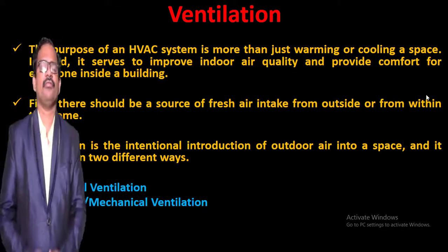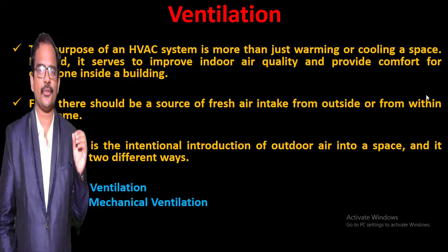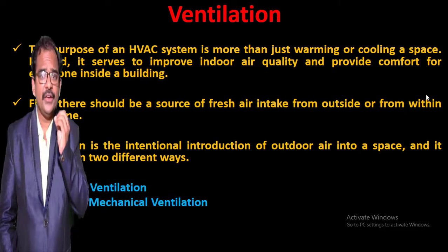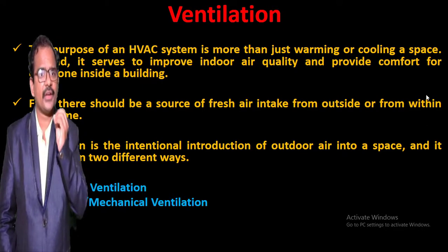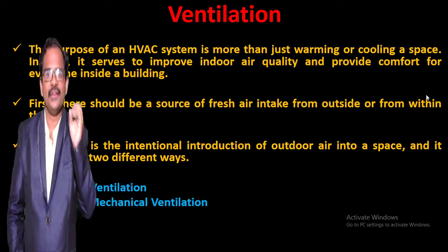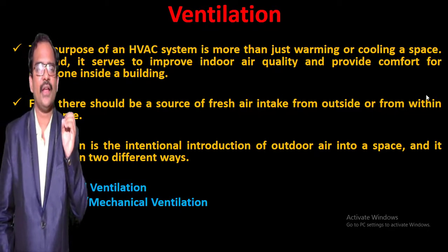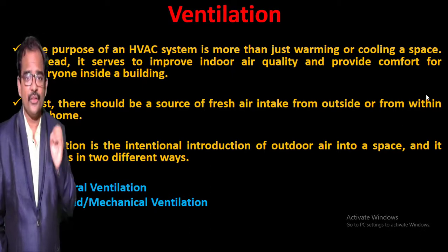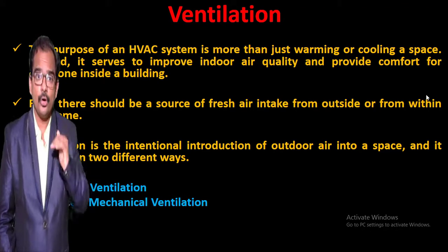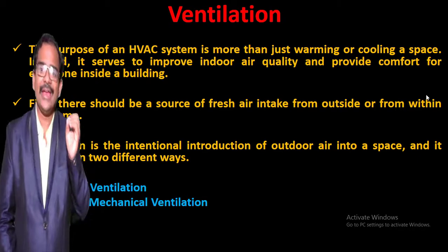Now let's talk about the first module, that is ventilation. The purpose of an HVAC system is more than just warming or cooling a space. Instead, it serves to improve the indoor air quality and provide comfort for everyone inside the building. The main purpose is to improve the indoor air quality, and that task is known as ventilation. First, there should be a source of fresh air intake from outside or from within the home. In order to have proper ventilation, we should have a source of fresh air intake.